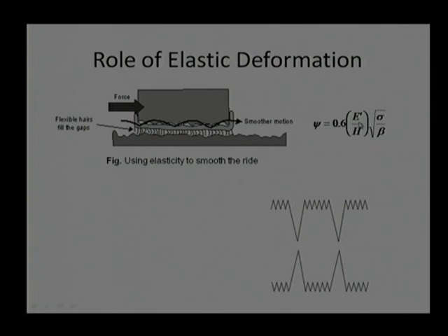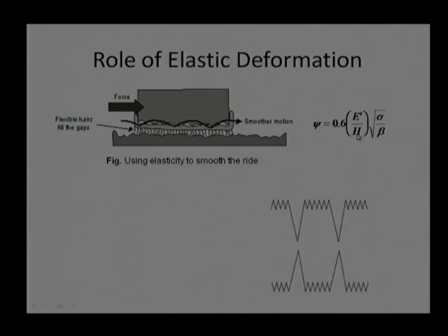It's interesting to note that we are emphasizing a low Young's modulus. Low Young's modulus will reduce the plasticity index. In general mechanical engineering and other streams, we generally prefer a high Young's modulus, but from the tribological application point of view, we prefer a low Young's modulus. That's an interesting thing. In addition, we have another parameter, hardness. Higher hardness will always be preferable. If you want a lesser wear rate, high hardness is preferable, and high hardness also reduces the plasticity index.